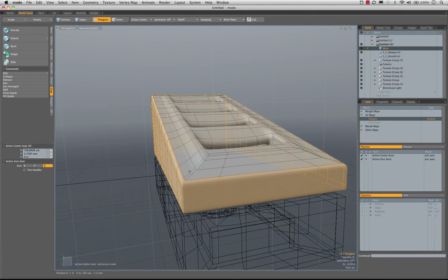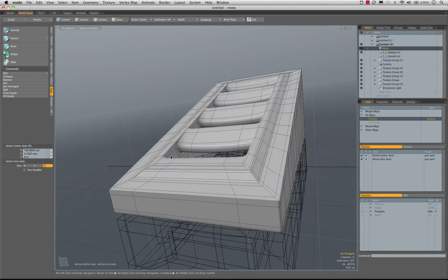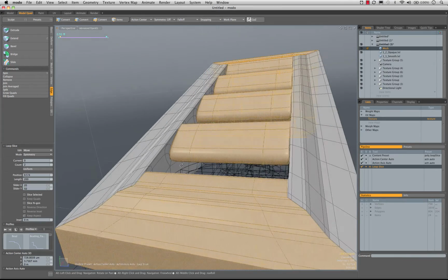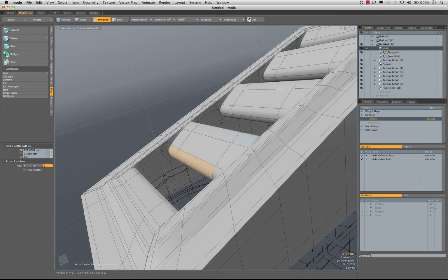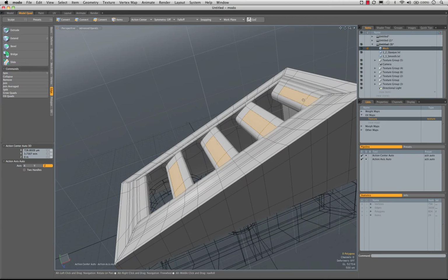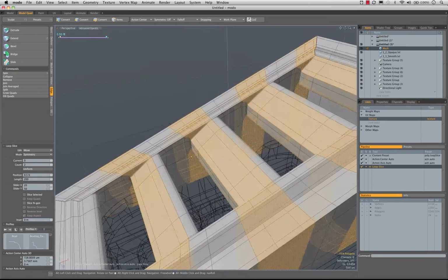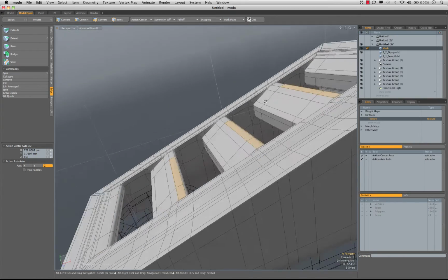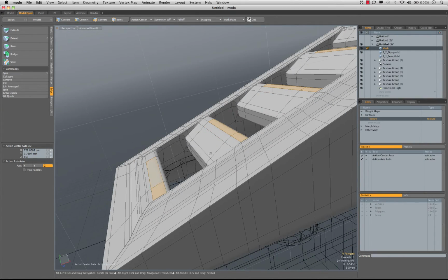So I'm going to go ahead and add loop slices here, here, here. Good. And now we need a second round of loop slices through these pieces, including this one. Good. We need them along the tops of these that will be the slanted edge. Good. And we need them along the backs of these that are the little solidified flat piece at the back. That back one won't need it. This one probably will though.